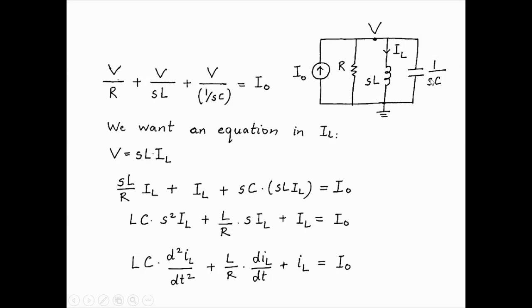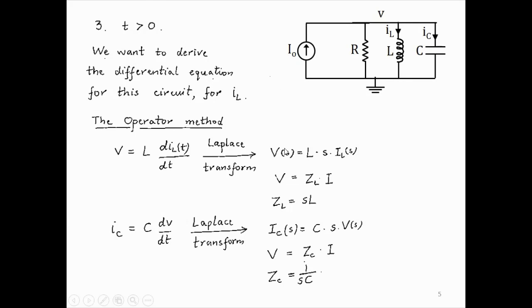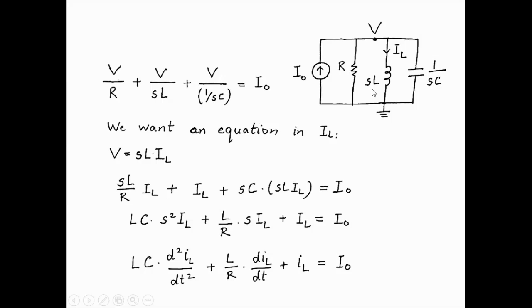So that is what is here. We just take the same circuit and replace L and C with these. And so what we did here was, instead of a derivative or a differential, we got an algebraic equation. So we use these algebraic equations so that we can write the KVL